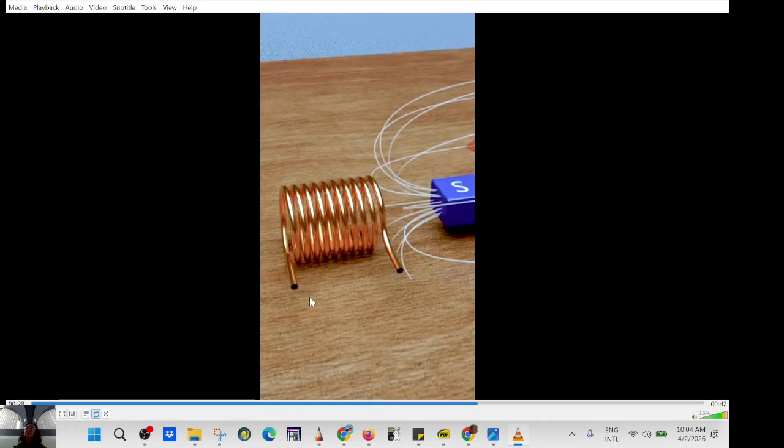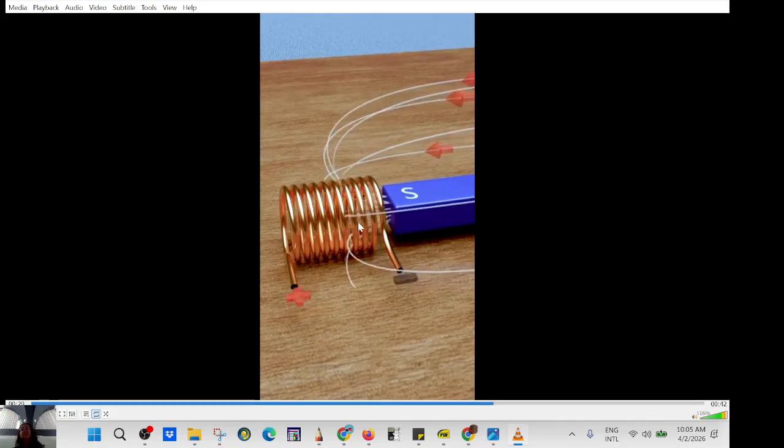So even though you are not closing the loop, so here you cannot induce current because the current cannot flow, right? But you are still inducing an EMF. You are still inducing a voltage. And sometimes in engineering, they will say you are inducing a voltage because the lines here are cutting through the loops. I say because the number of lines here increases and decreases, poking through the membrane. They say because the lines here are cutting through the loops. That's when you're going to have induced voltage.